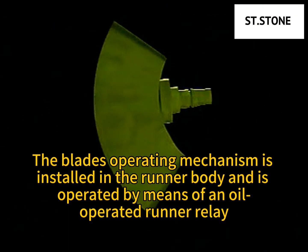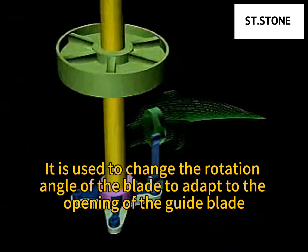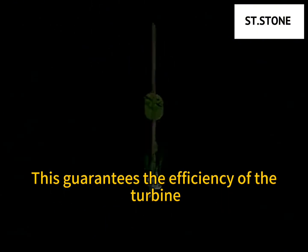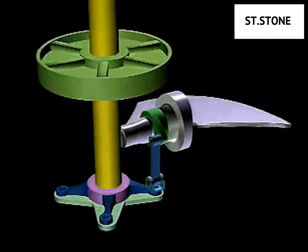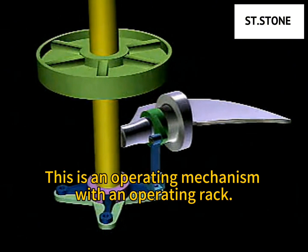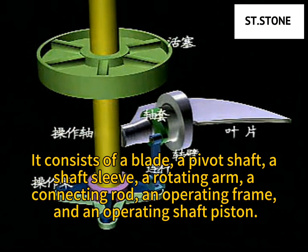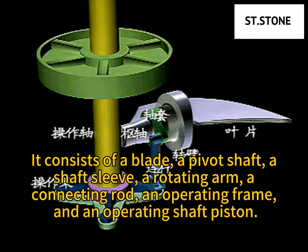The blade's operating mechanism is installed in the runner body and is operated by means of an oil-operated runner relay. It is used to change the rotation angle of the blade to adapt to the opening of the guide blade. This guarantees the efficiency of the turbine. The blade operating mechanism is divided into 2 forms. This is an operating mechanism with an operating rack. It consists of a blade, a pivot shaft, a shaft sleeve, a rotating arm, a connecting rod, an operating frame, and an operating shaft piston.